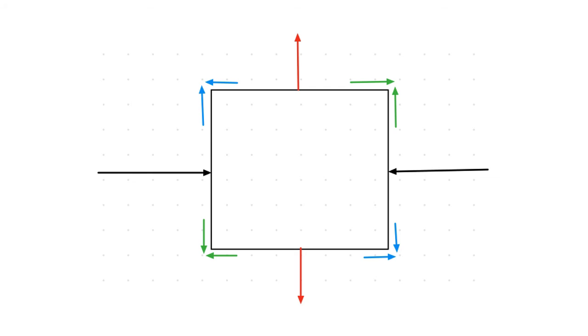So you'll see that the normal stresses in both black and red are opposite each other. And for the shear stresses in the corner, there are two pairs. The greens match up with each other and the blues match up with each other. The way we determine which one we'll be using is we'll do a little bit of math to see which one is greater. And I'll go into detail about that in the next slide. But as soon as one arrow is valid, all of the arrows in that same color are valid. So if we find that we're all in the green on the left side going down, all of our green arrows are true and valid, and the blue arrows, we just determine that it's the green arrows, the shear in the green direction.